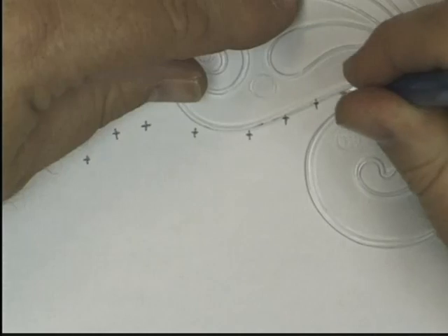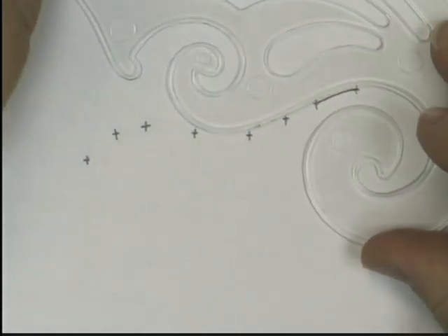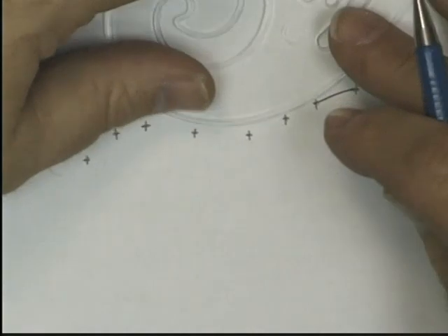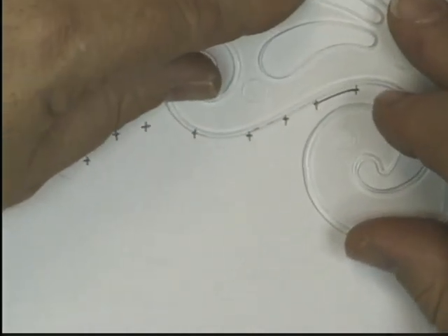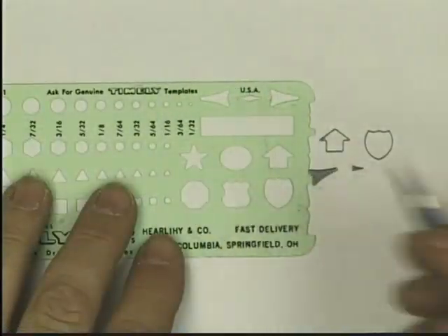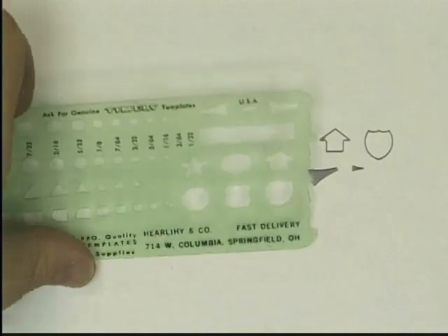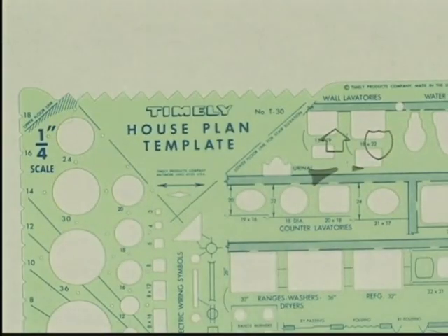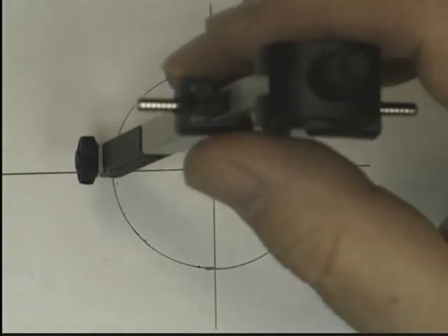Well, this completes our brief tour of some of the basic drawing instruments. We started out by playing follow the dot, by connecting a series of dots using a set of irregular curves, where the trick is, you might recall, to line up n dots, but to only draw n-1, and then we'll get a much smoother curve between the dots. Then we took a look at some of the many, many templates that are available. We took only a quick look. There are lots of these templates, and we saw how we can use templates for furniture, for making highway signs, or for making circles. And then we explored more arcs and circles through the use of a compass.